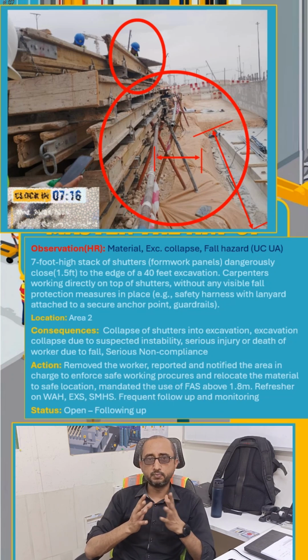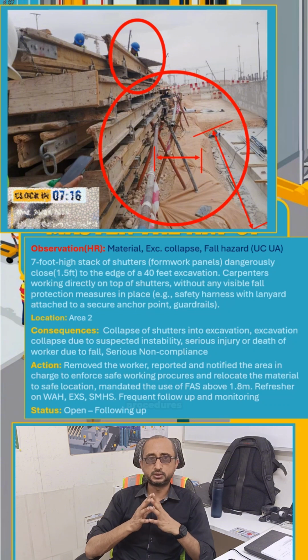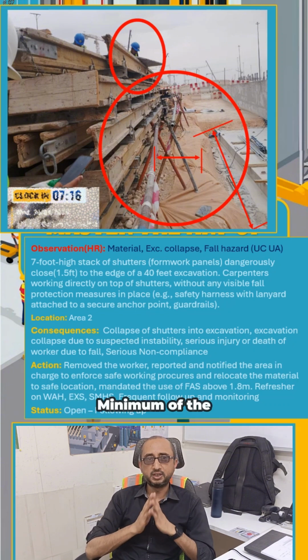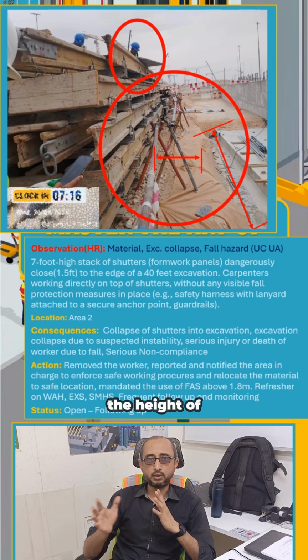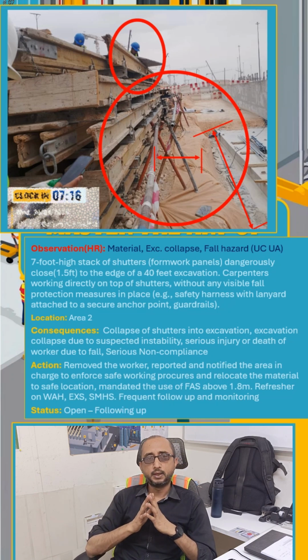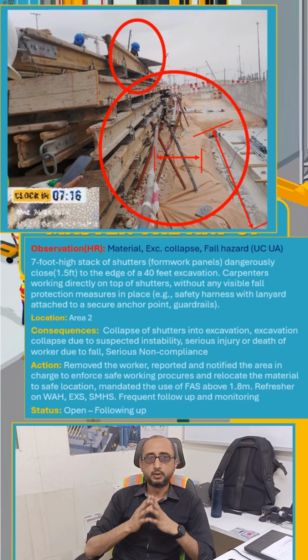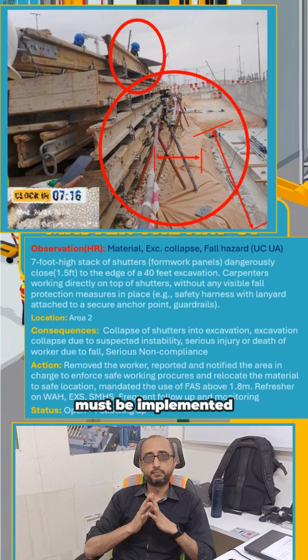At our work site, we have implemented very comprehensive standards approved by the client. As per these standards, excavation edges must be kept clear a minimum of 3 feet at all times, and the height of any stacking must not exceed the height of the barriers placed there. At the same time, for any work above 1.8 meters, fall protection and a fall arrest system must be implemented.